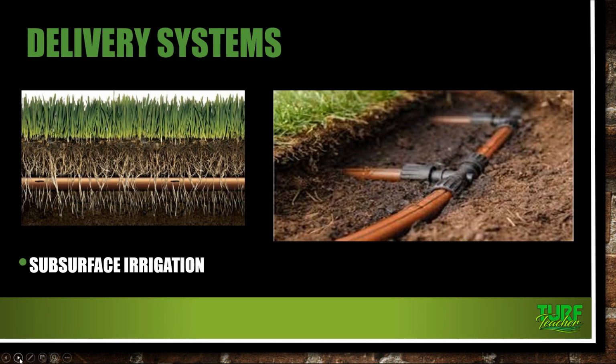Subsurface irrigation used on sod. It's really evolved over the last 30 years or so. But irrigating turf grass, ground covers, even shrub beds with subsurface irrigation eliminates problems associated with wind and overspray, guys, and that's a big deal. Not only is that wasting water, but you've got a windy day and your irrigation system comes on, and you're watering a courtyard in a commercial setting, and you've got workers and employees and even customers of the clients walking by, getting that mist and spray all over them.